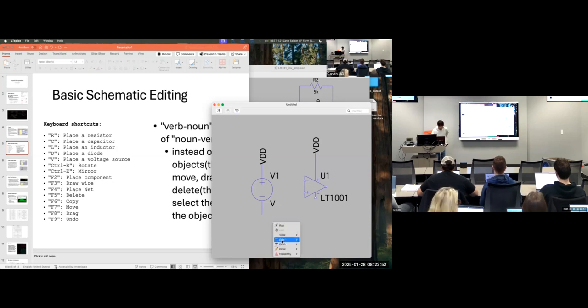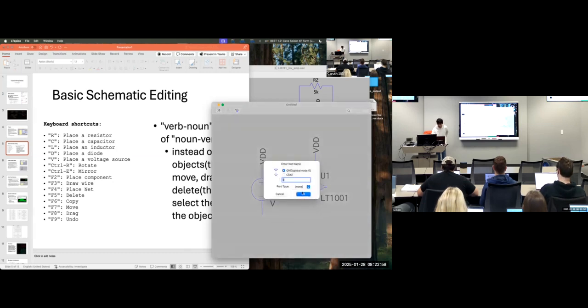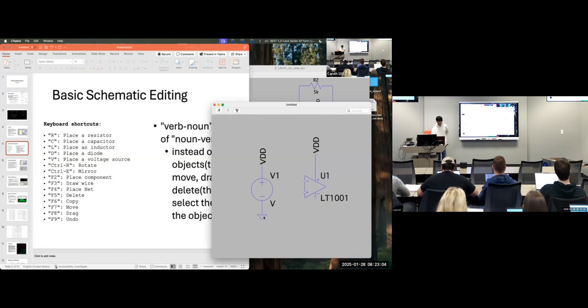Then I'm going to right click again. I'm going to go to draft, net name, and move around. I think I can press G for ground, but I can check later. I'll press ground right here. Escape. There we go. Yeah, G is for ground.